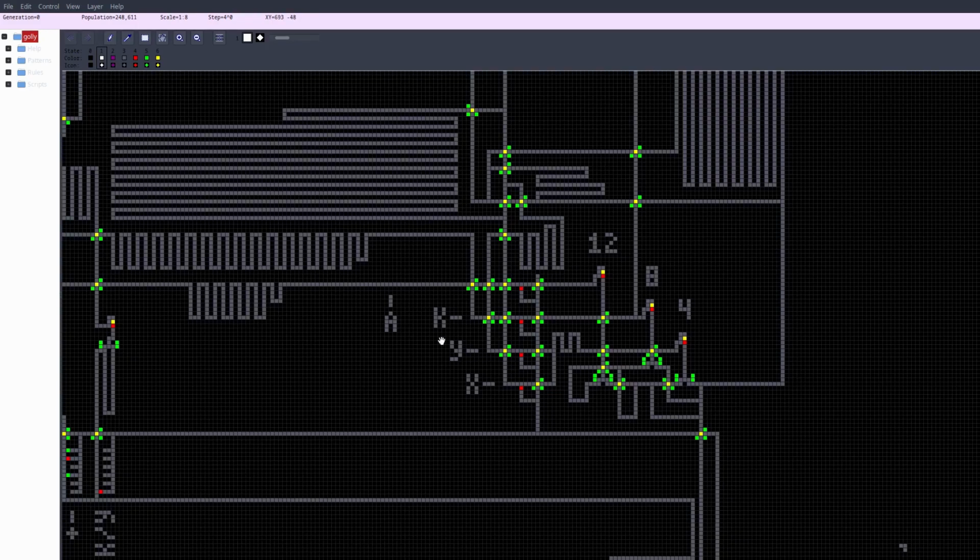This part here extracts the arguments from an instruction. X and Y, which are the addresses of registers, each of which, there are 16 registers, so the address for a register is 4 bits, or K, which is an 8-bit constant to be used instead of the value of one of the registers. A is the address to jump to. A is 12 bits, K is 8 bits, X and Y are each 4 bits. So these devices generate 4, 8, and 12-bit sequences, respectively, to extract that bit from the instruction.